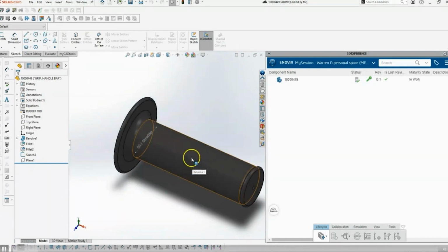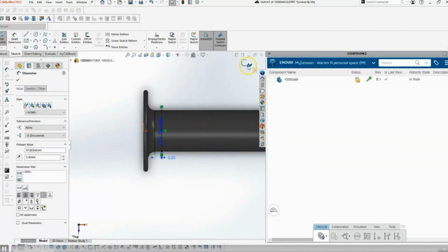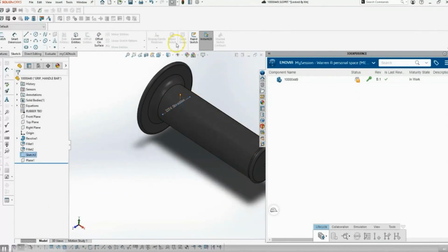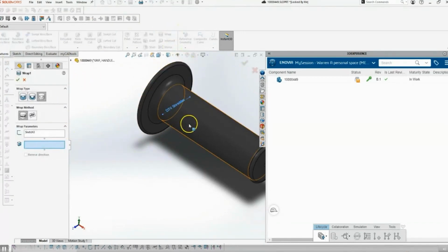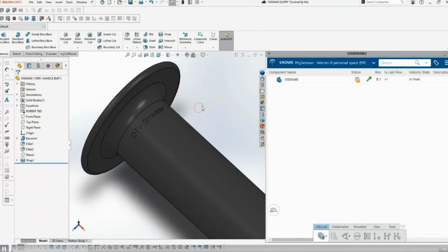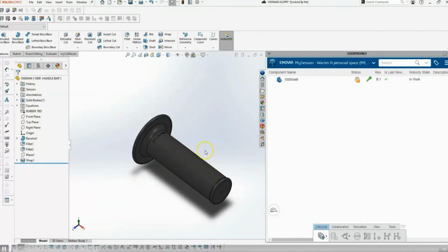And in the new version of SOLIDWORKS 2023, it allows you to add single line fonts like this. And I'm going to edit the sketch. And I'm going to wrap this around the cylindrical face because in 2023, it allows for something like that, to scribe over the cylindrical face like that, and beautifully, right? They didn't specify how close to the center I need to be. So I'm just moving it a little bit closer to the center.